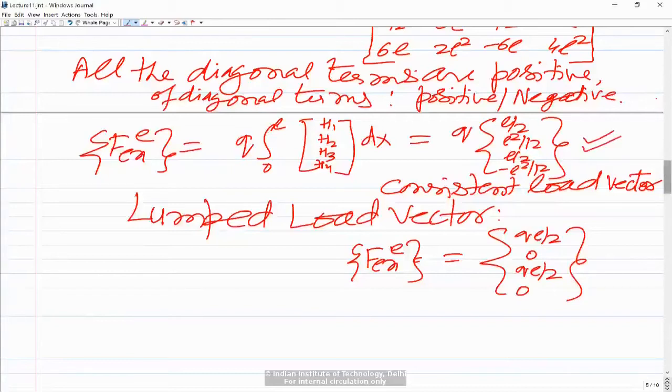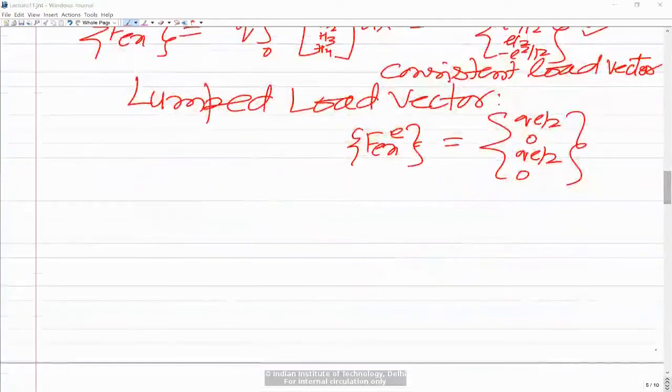So once we have this, you can use the element to solve problems. Let's look at the applications of this Euler-Bernoulli beam element for solving simpler problems. Of course, you can solve more complex problems, like the entire network of rings and stiffeners in a submarine. All the stiffeners and rings would be subjected to transverse load, and you have to discretize the whole thing into a certain number of elements, then assemble, impose the boundary conditions and solve the problem. That is a more complex problem.